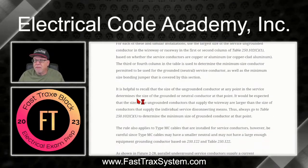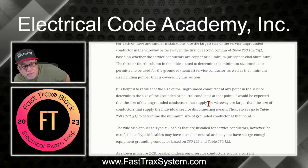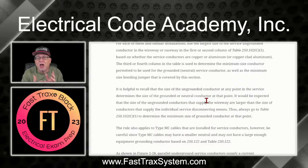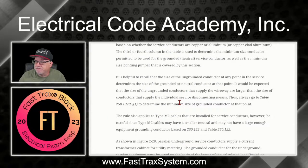Okay? Now, it is helpful to recall that the size of the ungrounded conductor at this point is the driving factor for sizing that neutral, of the minimum size. It's the driving point. That's why we took those ungrounded conductors and used them with that table to be able to size it. So it's important to remember that when you're doing that.